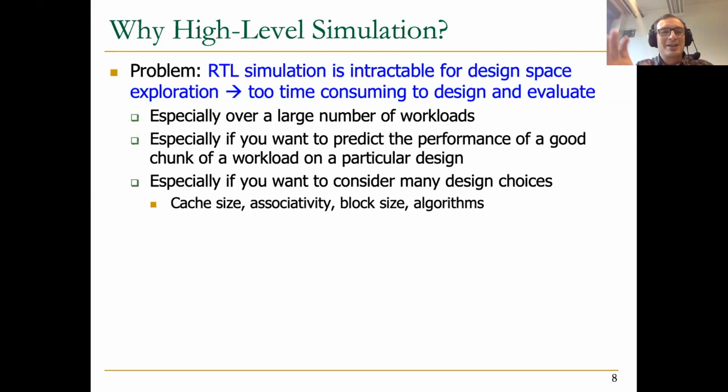In fact, you can do some calculations if you're really interested. RTL level simulation is usually much slower than, let's say, 1 kilo instructions per second. I'm saying it's actually orders of magnitude slower than 1 kilo instructions per second. So if you want to simulate 10 seconds of execution, you can imagine it's not going to work out well, right? Basically, this is too detailed. I will say intractable for making design choices, if you want to consider all of these things that we discussed. If you want to consider only 100 instructions executed in some workload, maybe 3 or 4 workloads, or let's say even 100 workloads, then this may be okay.